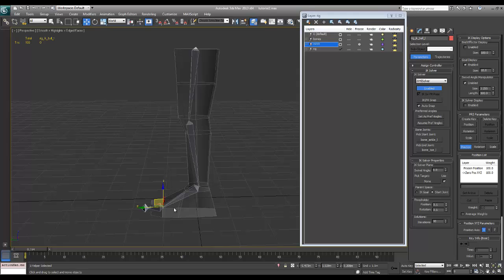So I'm going to do a simple setup for a foot, and it's going to incorporate 3 point helpers that we're going to align with each one of these IK constraints, and we're going to link them together, and those will control the IK solvers, and then later we're going to attach controller objects to those to help make it more visible, which will be our shape controllers.